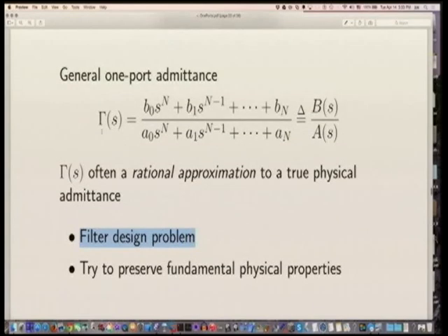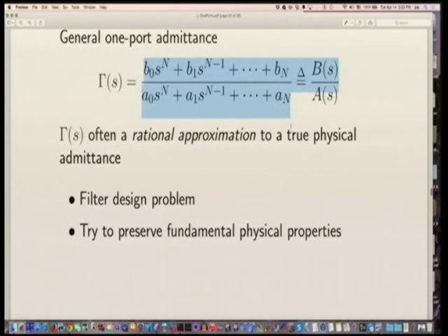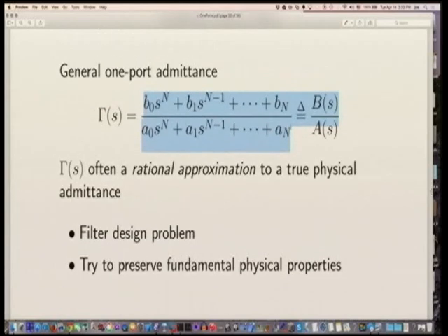And so you take your measured mobility and fit a filter with something like invfreqz or LPC, whatever you want, really. Just go through the MATLAB toolbox, say help filter, and look at all the filter design capabilities in the filter design toolbox, which is extensive in MATLAB. And I do believe we have that. Just try things out, get good results, plug it in, and you're happy.